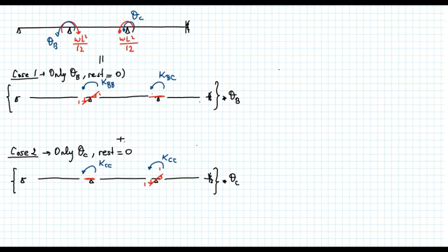So let's draw the deformed shape due to that rotation. So this end is free to rotate. So I have this is equal to 1. And the deformed shape of the structure will be like that. That's equal to 1. Second case, 0 rotation here and unit rotation at this end. That's equal to 1. And this is equal to 1. So let's go member by member, and for each member, calculate the end moments due to the rotations.